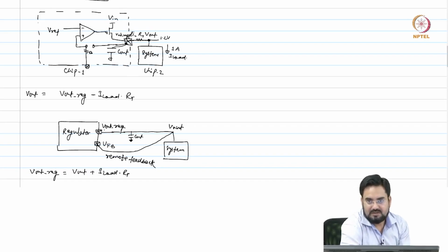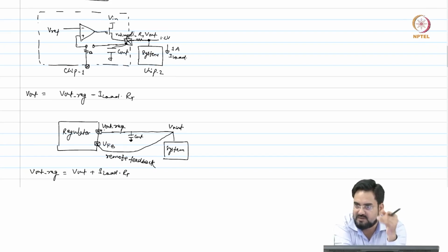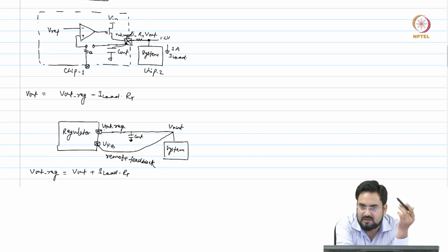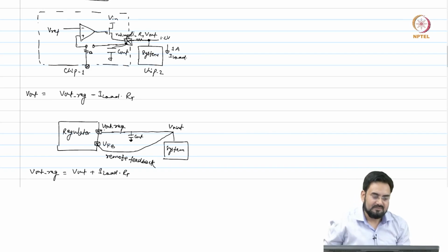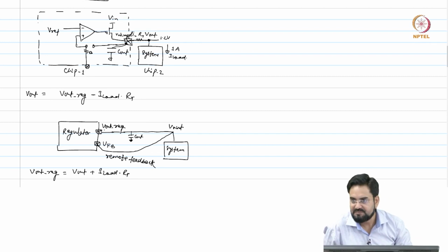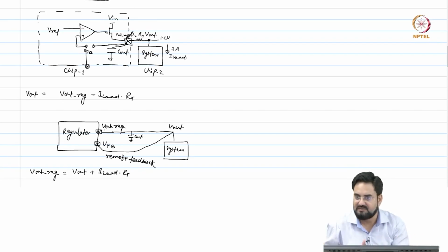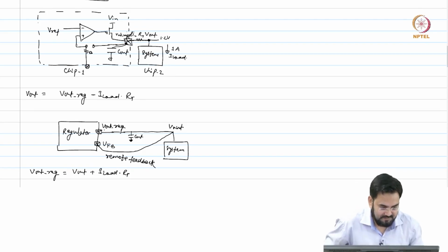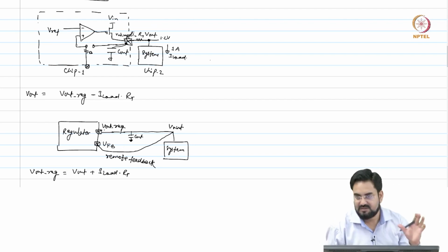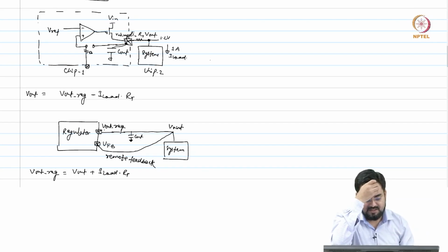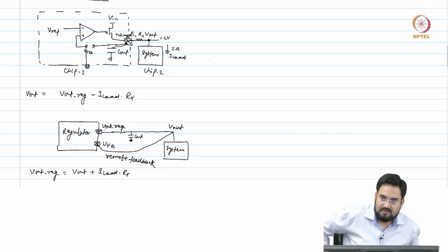It all depends on how much you gain by doing that, and sometimes you may have to underperform your system also, because if you want 1.2 volt to run at full strength, but you are supplying only a lower voltage, then that means you cannot run it at full strength. So, your system is forced to run at lower supply and lower performance. So, overall it may not affect efficiency much if you consider both the cases. In one case you are gaining from your system efficiency, in the other case you slightly gain from your dropout voltage. I square R loss is in both the cases, because the resistor is there and current is flowing. So, whether you do it or not, your I square R losses will remain. But if your accuracy is more important, then you do not have any option, you have to do this. Is there any other way I can fix this without putting this feedback?